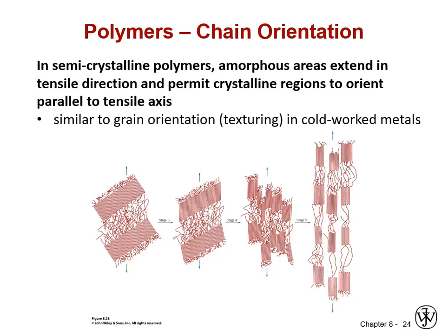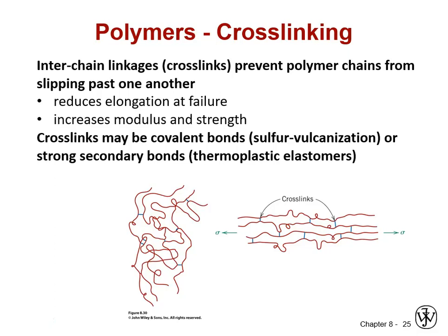And this is of course why polymers tend to deform viscoelastically. Those amorphous regimes, they literally do flow, especially if we give them a high enough temperature that they can move quickly. That is, unless we put a covalent bond across them. And that's what cross-linking does. So thinking about strengthening mechanisms for polymers and thinking about thermoplastics in terms of viscous flow and chains literally slipping past one another in those amorphous regions between crystallites.